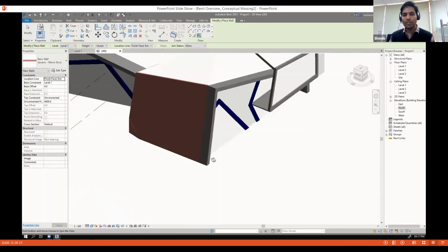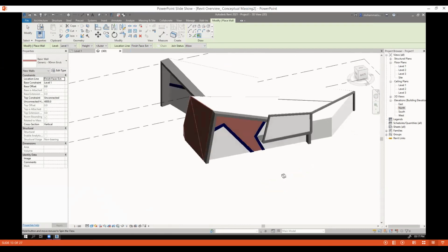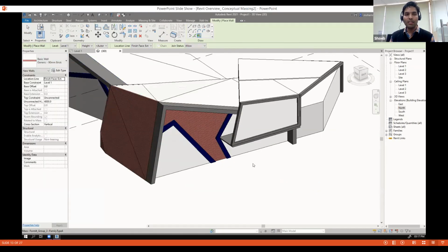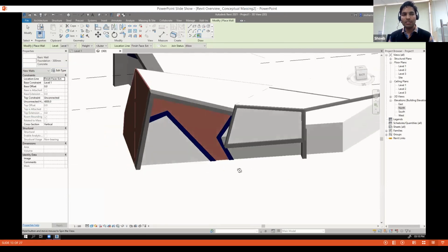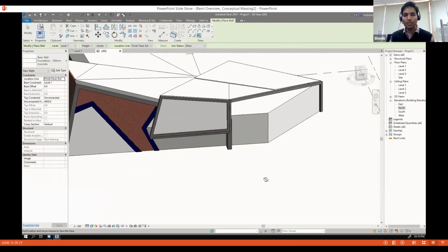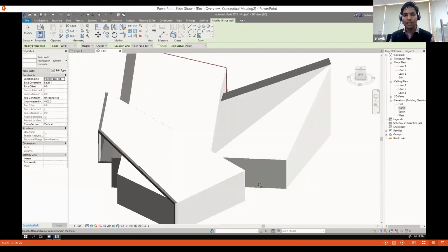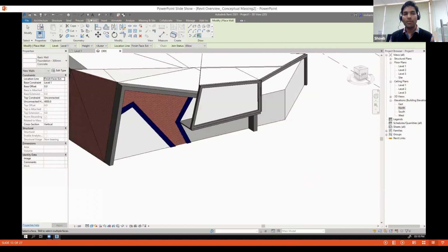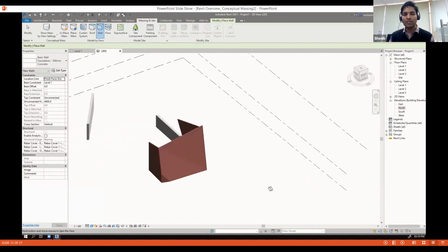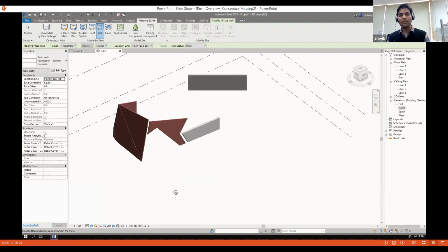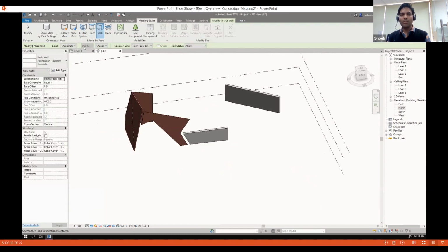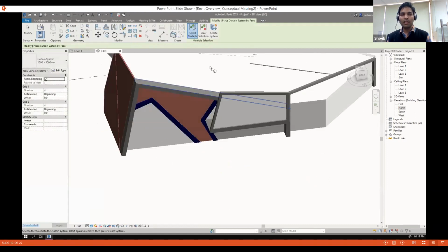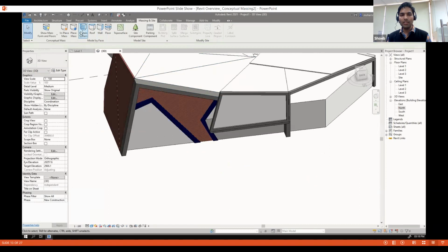You can just put up these walls by picking those faces. So that model is an interactive model, and now I just changed the wall also. I'm putting some concrete walls here. And if I want to check the Revit progress, I can switch off the FormIt model by clicking on visibility settings. So now, as you can notice, it is converted into Revit components. And then similarly, I'll add a curtain system there.